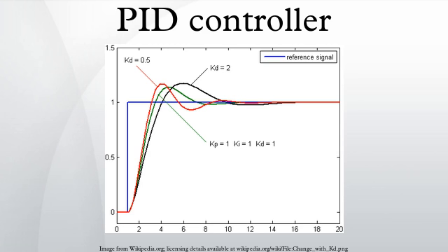PI control yielded sustained yaw of plus or minus 2 degrees. Adding the D element yielded a yaw error of plus or minus 1/6 degree, better than most helmsmen could achieve. The Navy ultimately did not adopt the system, due to resistance by personnel. Similar work was carried out and published by several others in the 1930s.